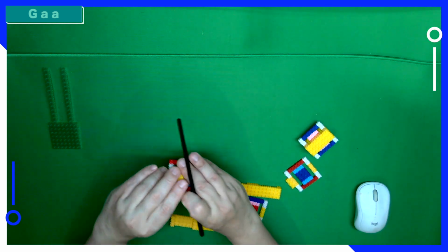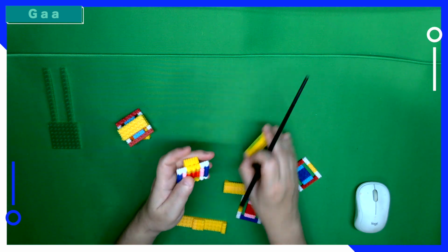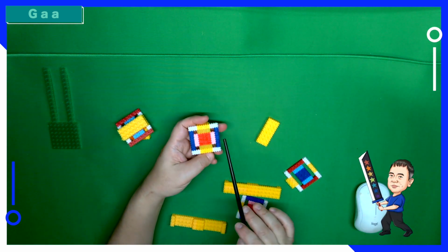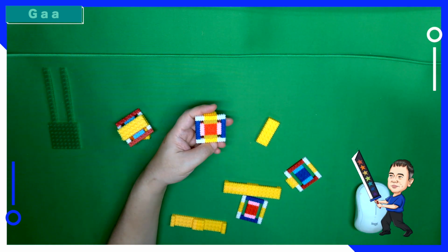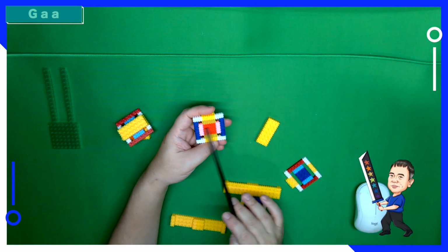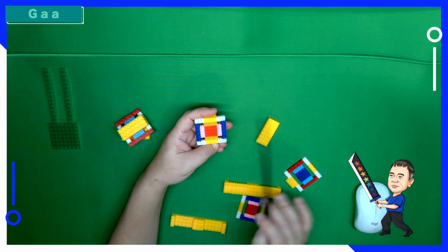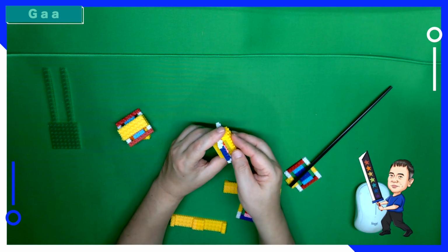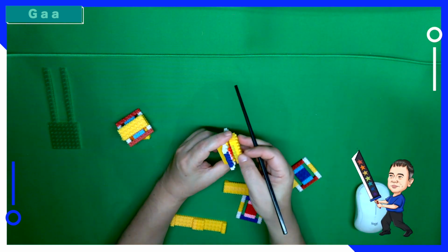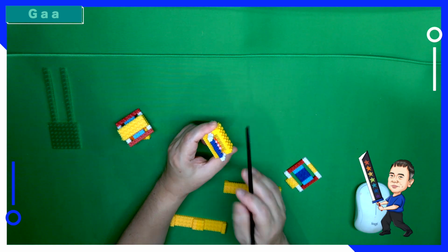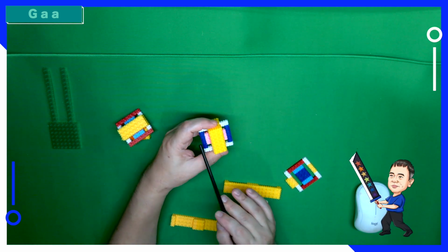The same way we can do it for the positive channel. So positive, positive, and when you apply negative voltage, the current will go through from positive source to positive drain as well. I have a gate here, gate on the bottom, and gate on top. So that's the gate all around for the P channel.